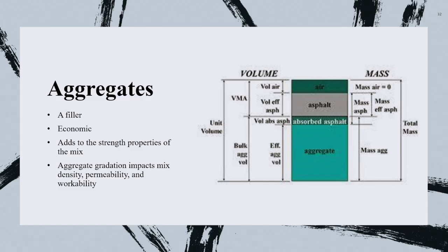It is like, if somebody has done lightweight concrete construction here, you have expanded shales or clays. I've done a few projects for bridge decks using lightweight concrete because you want to reduce the dead weight of the bridge deck. So if you use lightweight, it has a lot of voids in it. If you mix it straight in the concrete, you will never have a concrete mix.